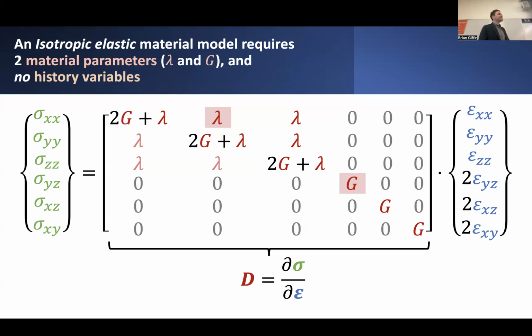Yeah. So nonlinearity in materials wouldn't change the modulus. If it changes the modulus, that means this matrix would change. Right. So there are ways that you can augment the stiffness, and I'll talk about that momentarily through maybe some kind of internal damage mechanism. So let's say that if the material stiffness were to degrade because you subjected it to relatively large strains and then it loses some of its elastic stiffness, I would call that a damage mechanism.